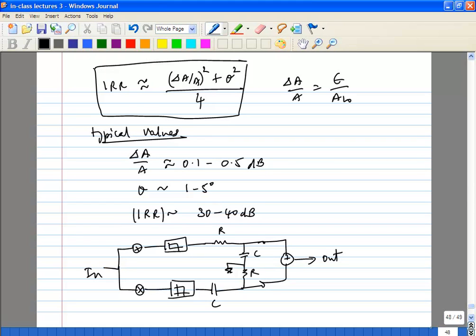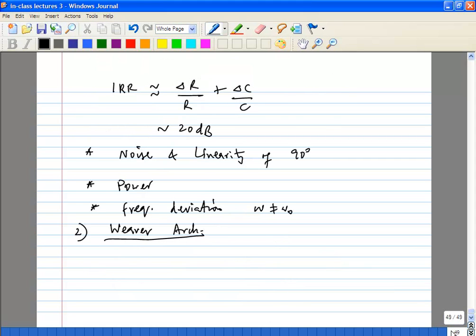The half IF problem is independent of what you're doing here. You could still have the half IF problem, definitely. So you should still try to minimize the second order distortion and so on. Here you're just trying to kill the image, nothing else. So what you're going to do is replace this shift by 90 with a second set of quadrature mixers.